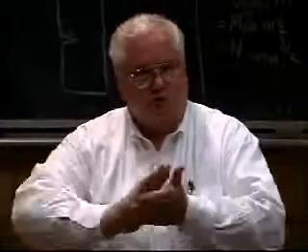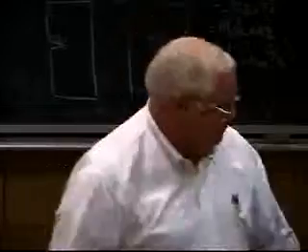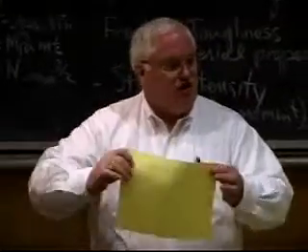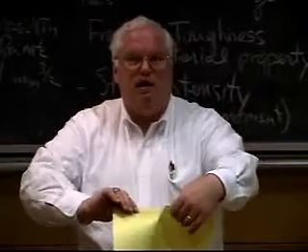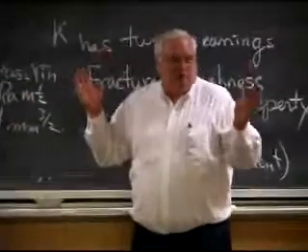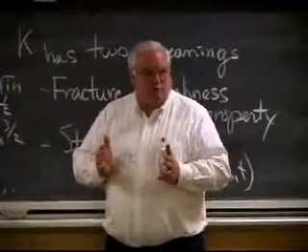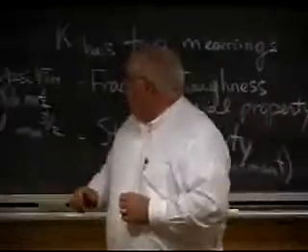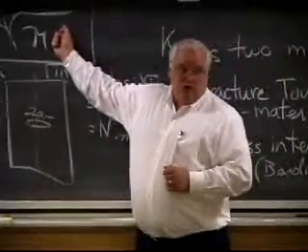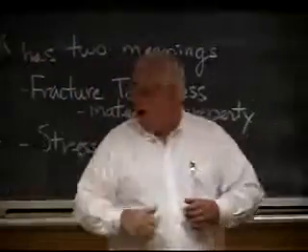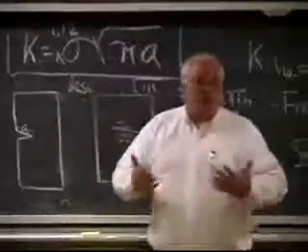If I have shear, okay, if instead of pulling on my paper this way, I'm shearing the thing, I'm ripping it this way, then you have a different fracture mode. And so I would actually have to go to that textbook and look. Okay? And maybe there's a factor of 2 difference. But in general, if I want to be accurate within a factor of 2 in terms of estimated critical flaw size, which is in the square root, remember? So if I want to be accurate within a factor of 2, I only have to be accurate in my stresses or my geometric effects within a factor of 4.